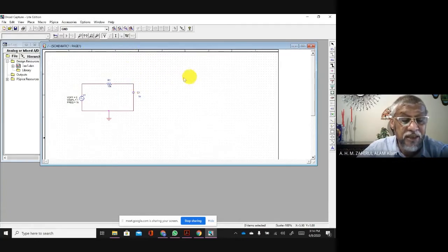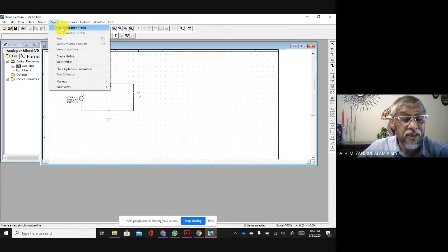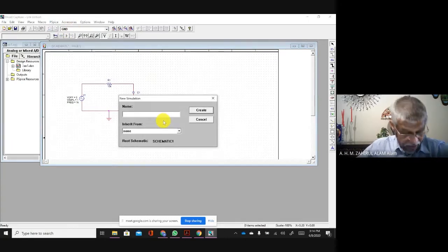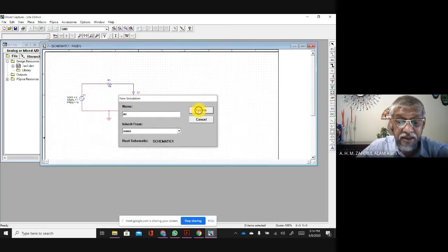Now I need to simulate. In order to simulate, I need to go to the PSpice menu up there and create a new simulation. I can name it any name, but I name it AC, then create.